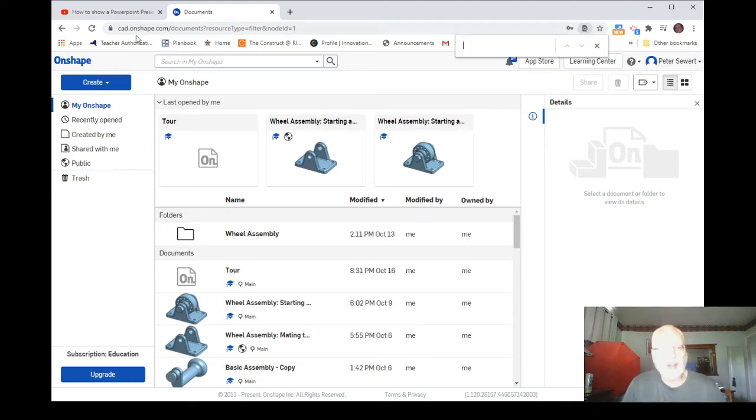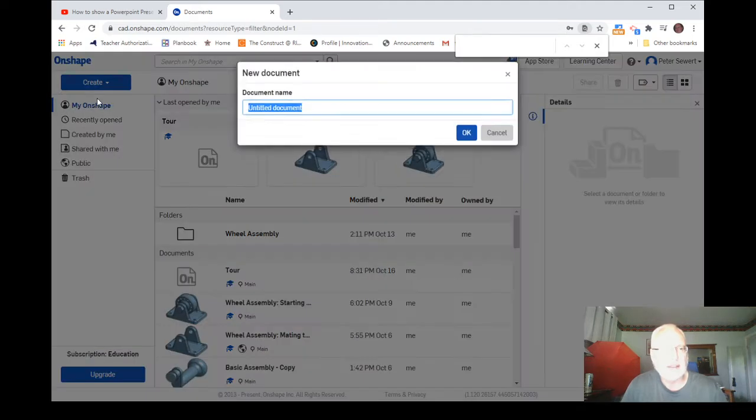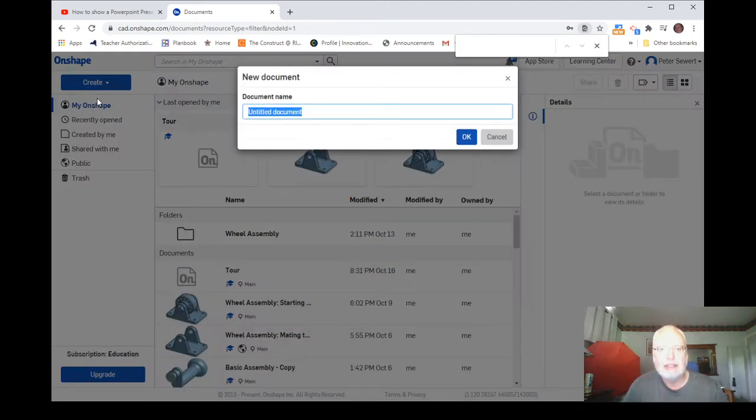So this is your Onshape program, and you guys have seen in the introduction video already the little tour that we took. So I'm going to go to right below the word Onshape. There is Create, and I'm going to click that. I'm going to select the word Document, and then I'm going to name this document. So I have to put in an appropriate name.